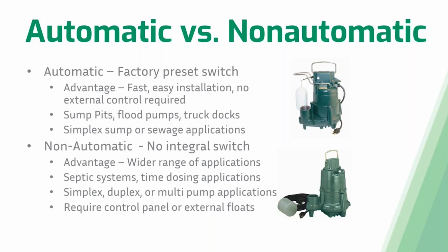You also need a non-automatic pump for time dosing applications where that pump is going to be turning off after a certain period of time rather than whenever a float switch goes up. You can use these pumps in simplex, duplex, or even more pumps in an application than just 2 or 3 or 4. And lastly, as I've already mentioned, these pumps will require some kind of external start component like a control panel and external float switches as well.